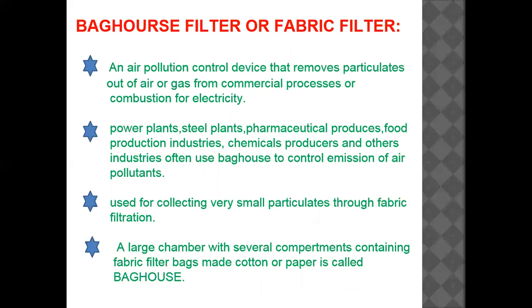This control device is effective for very fine particles less than 5 micrometer in diameter. It is used in power plants, steel plants, pharmaceutical industries, food production industries, chemical industries, and other industries to control emission of air pollutants. It is used for collecting very small particles through fabric filtration.